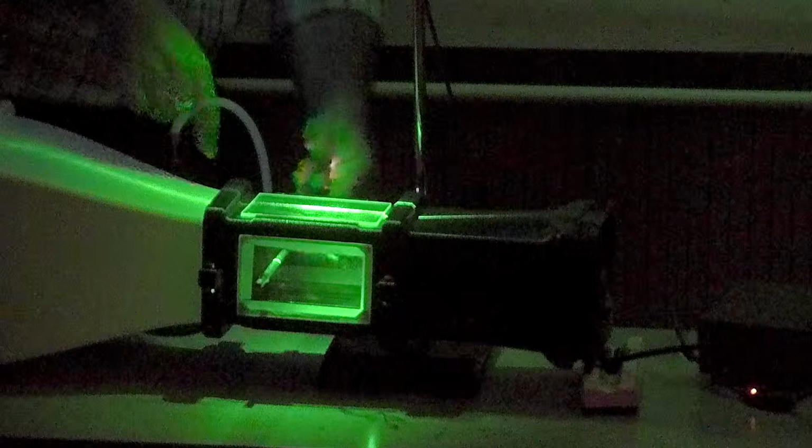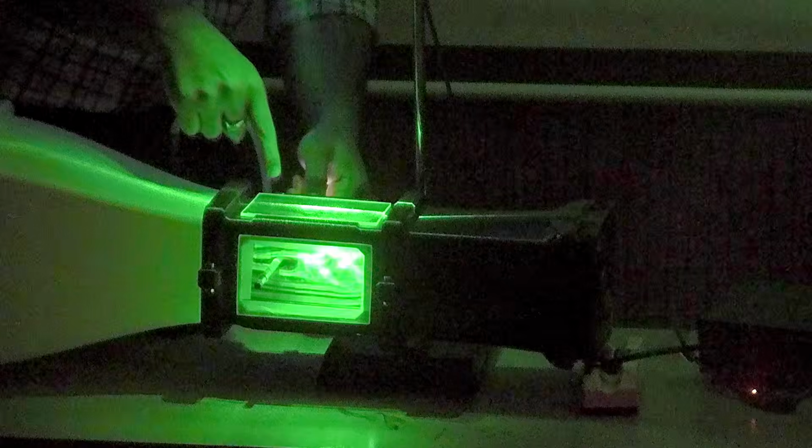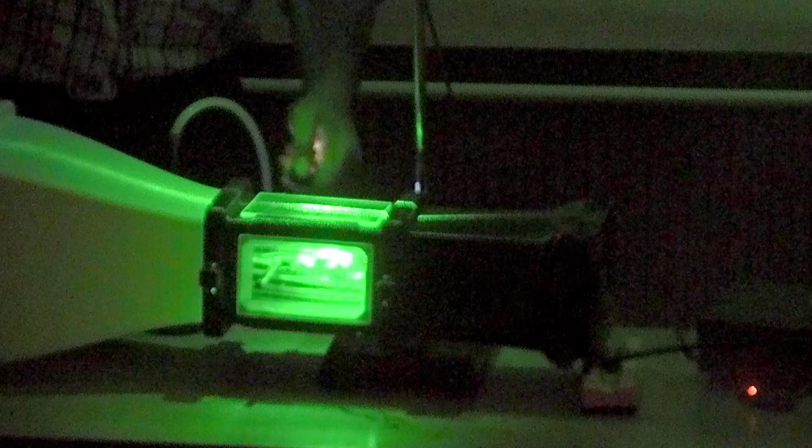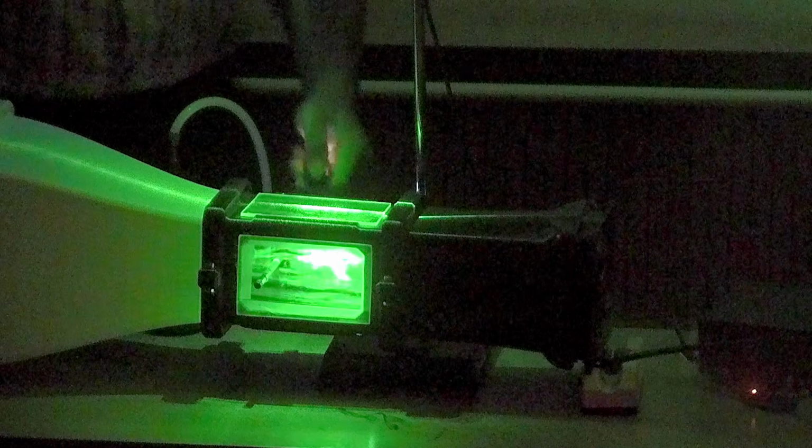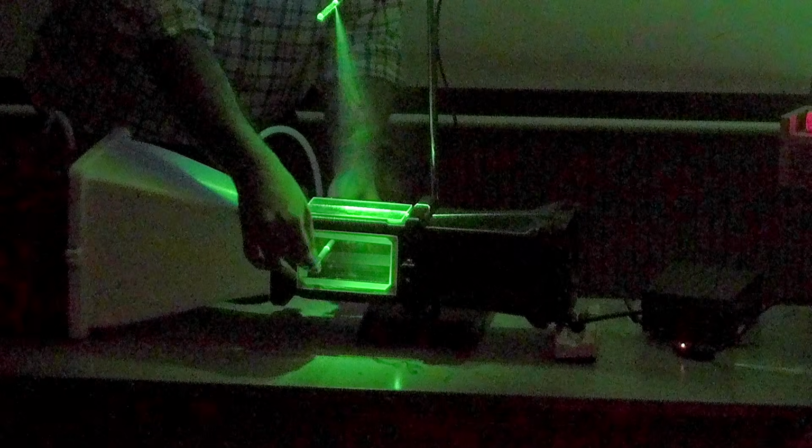you see what I was talking about, that there is a boundary layer separation that is happening. So right above the cylinder, there is a boundary layer forming, and due to the dp dx becoming positive, pressure increasing as you move further downstream, you see that your boundary layer is actually separating from the cylinder surface. Okay, and you can see this in other type of cases as well.